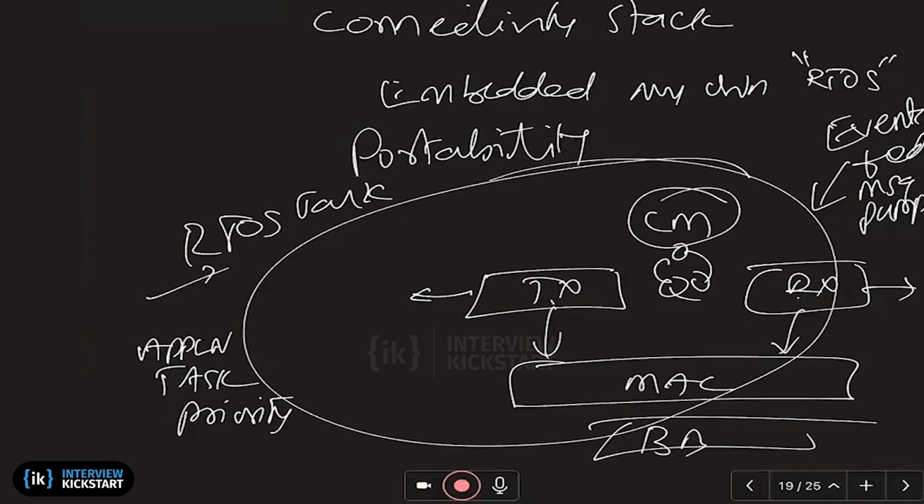So it's not a purely technical thing, but if you want to prioritize, look at dependencies, number of IOs, or how complex the thing is. How many tasks are you managing? So if it goes above a handful, an RTOS is definitely worth it.